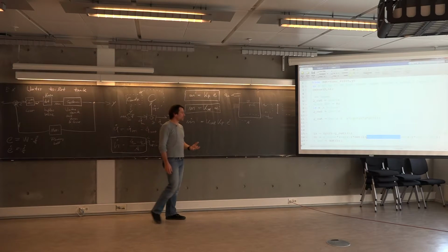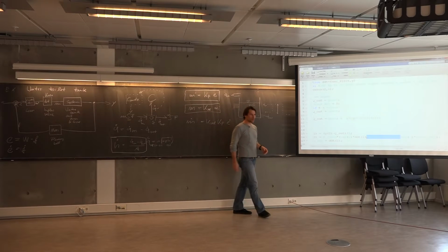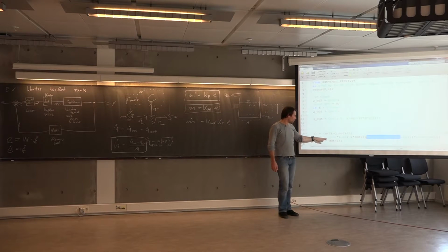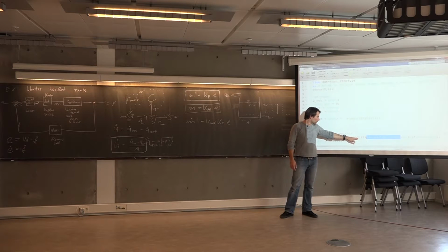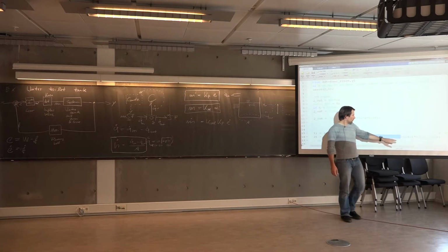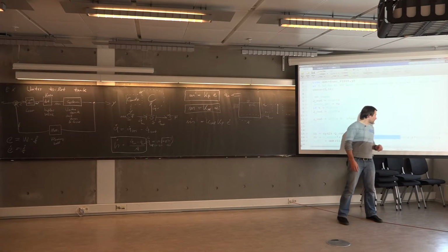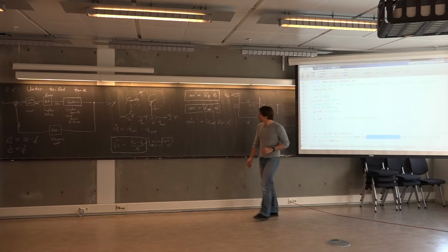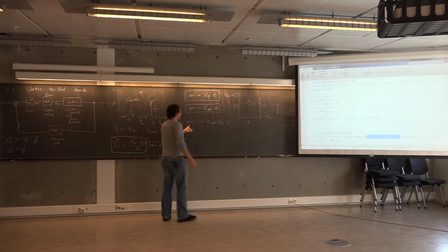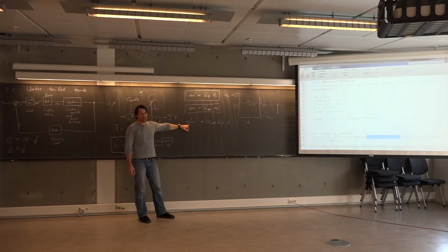This is the combination as it was just shown on the PowerPoint slide. We have this proportional term, and we have the derivative term. Again, we use this concept here. We take the derivative of the manipulated variable so that we can solve this equation over time.